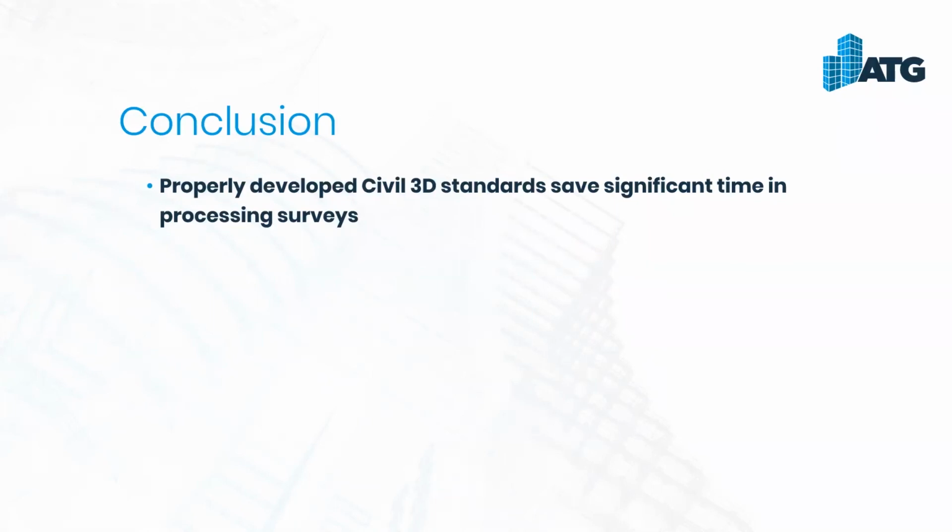You know, doing that might have taken a full day to go out and shoot in the field, but in the office, processing that survey might take us an hour. Whereas if you're just going out and collecting points and then taking those points and drawing your own line work and manually assigning them all to the right layer and doing the rest of that stuff, you're going to be going through a lot more effort in the office. So yes, it does take a little bit more time, maybe an extra 30 minutes all in for going out and shooting that site in the first place.